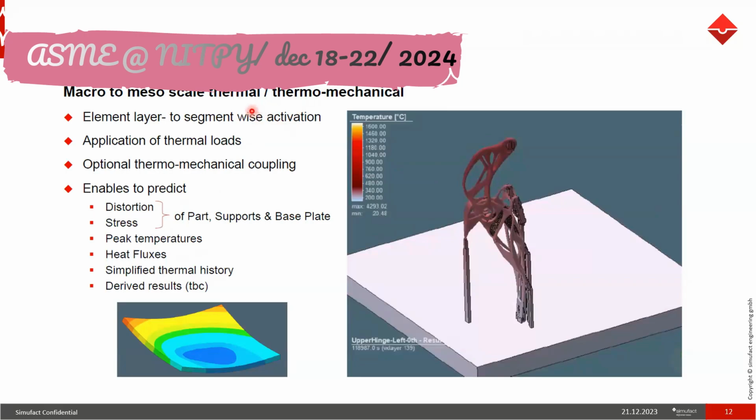But what is the disadvantage of the thermomechanical approach? It is very slow, because it has to calculate the thermal strains, put them into the mechanical analysis, and then calculate mechanical strains, then distortion and stress. So it is a time-consuming process. That's why in some cases we avoid the thermomechanical approach for additive manufacturing processes. We follow the inherent strain approach most of the time.